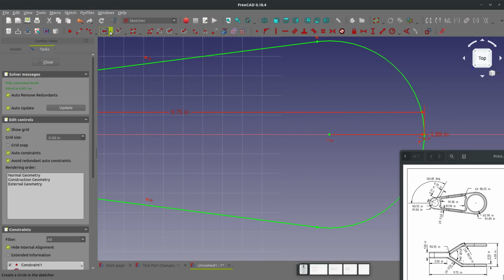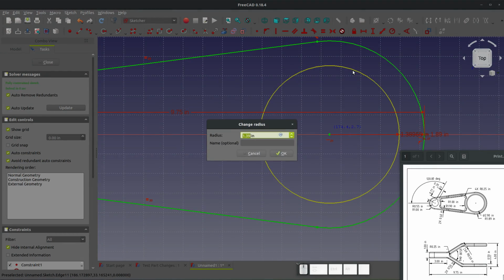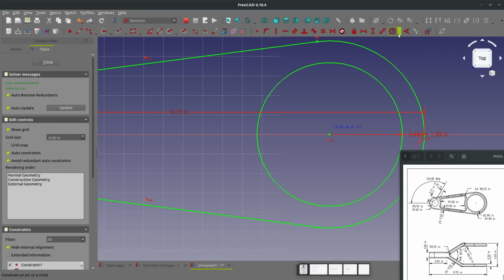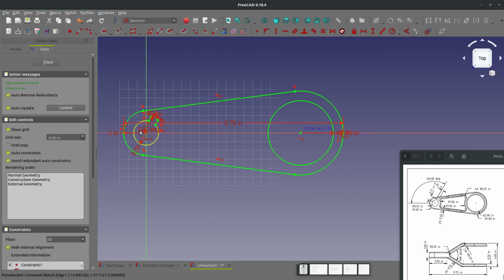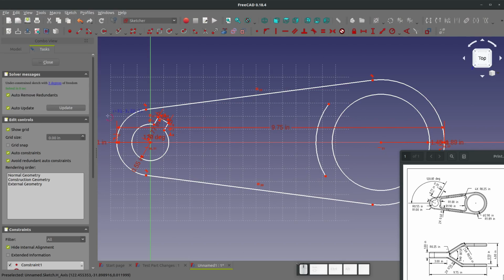Next, we're going to create a circle, and we have a diameter call out for the circle. It's 2.9 inches. So we'll give a Shift R, and we're going to say 2.9 divided by 2. You also can select a diameter, but I just leave it on radius and divide by 2 because it's easy to have one thing instead of switching between two tools. Purely personal preference. I'm going to go back to a center and end point radius, or arc, and grab these and these.